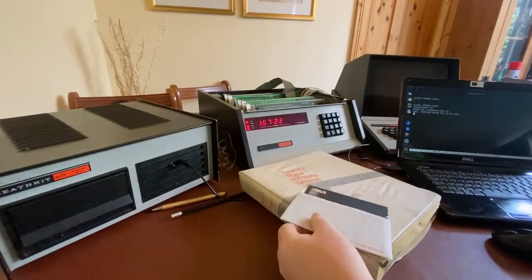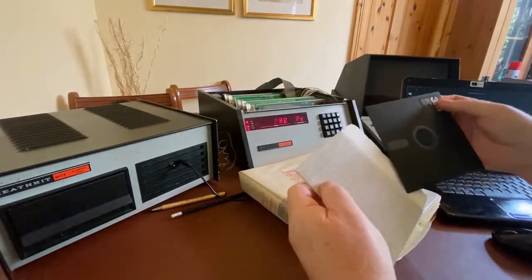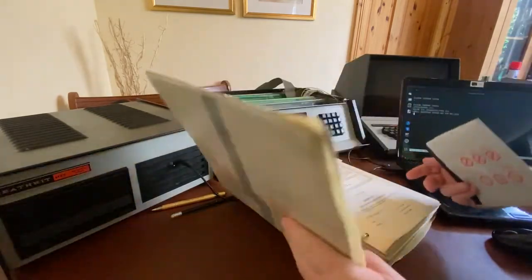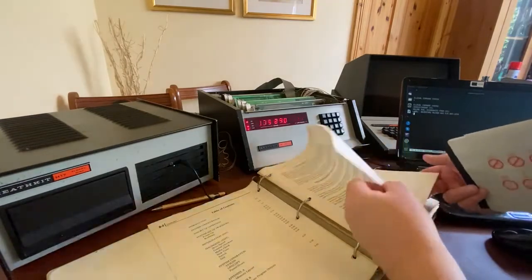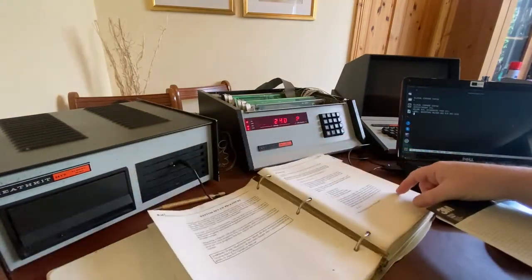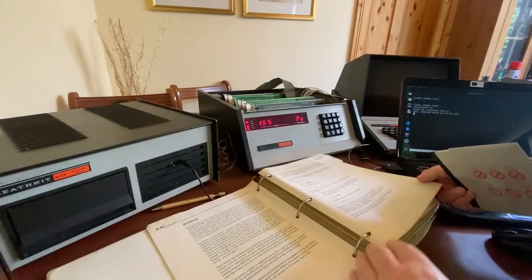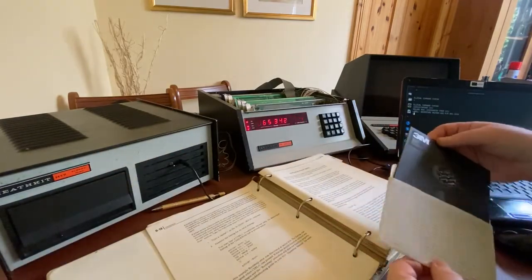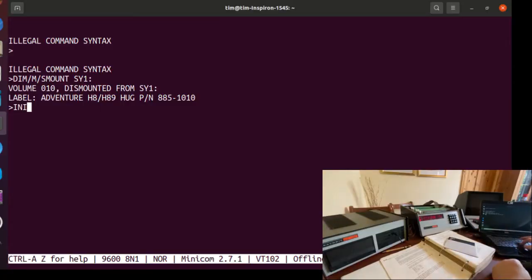So now we're going to look at our floppy, and we're going to learn how to format it and deal with it from the Heathkit manual, which you would have followed. Obviously I've been through this once to prove the drive is functional, which has got quite a bit of theory and files and how it works, how to power up, which we did, to boot, the boot prompt, which you've seen, and setting the date, and now initialization to prepare the disk for processing. So we're going to start the init program.